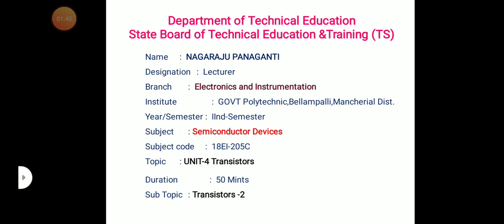So we have three terminals in the transistor and three layers, PNP or NPN, and we have two junctions. The emitter base junction is called the emitter junction. The collector base junction is called the collector junction. The emitter junction is in forward bias and the collector junction is in reverse bias. So this type of biasing is called active biasing.